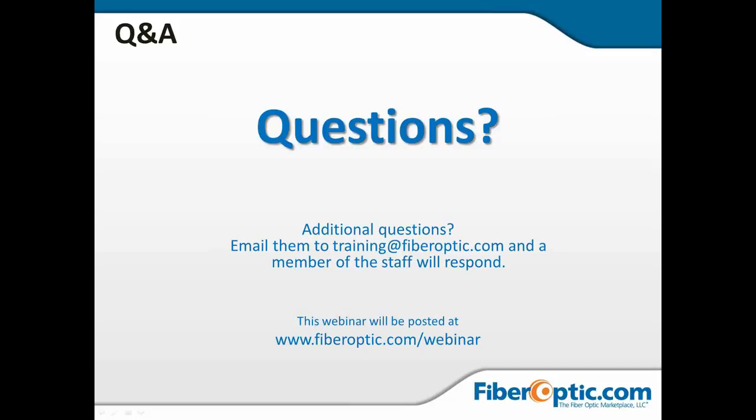DirecTV requires 2.2 gigahertz plus. Do I have any suggestions? One suggestion would be to put in a head end at your receive site. Receive all of the signals and then look at how you want to distribute that through the units. If you go ahead and process it and get the raw video and raw audio, go ahead and get your channel information. Then you can go ahead and process that and then recombine it and insert it.